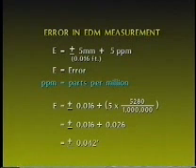This equation indicates that there is an error of plus or minus 5 millimeters in every measurement, regardless of the length of the line, plus an additional error which is dependent on the length of the line. This additional error is a proportion to the value of 5 parts in a million. What this means is that if we could measure 1 million feet with this EDM, it would create a 5-foot error. By proportioning this ratio to the length of the line being measured, we can determine the total error.